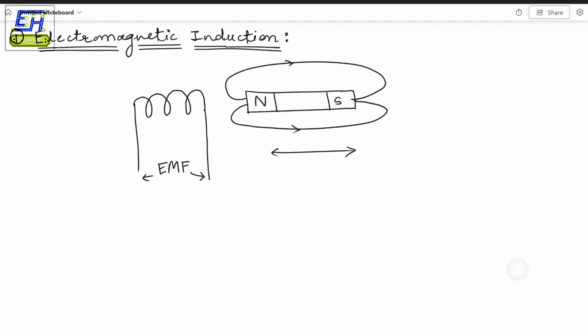And the other way you can change the magnetic field is simply by rotating the magnet itself. And this is usually what happens in electrical generators. We have a rotating magnetic field that we use to generate the EMF or electrical energy, because it is very easy to have continuous rotational motion, as compared to just this linear vibratory motion, which is ultimately driven by the shaft of the generator, where you provide the mechanical input through, say, a turbine.